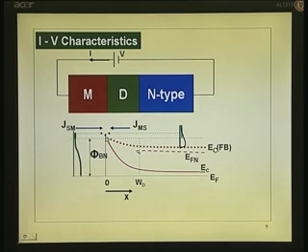So, if there is electron concentration N s at the surface, and they have a velocity component V x in this direction, due to their kinetic energy, that is due to the temperature, they have got a certain velocity V x. Supposing n is the concentration, V is the velocity, what is the current? N into V into Q, as simple as that.